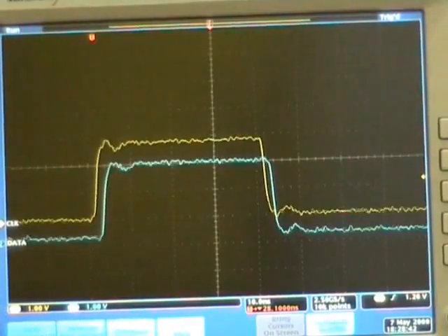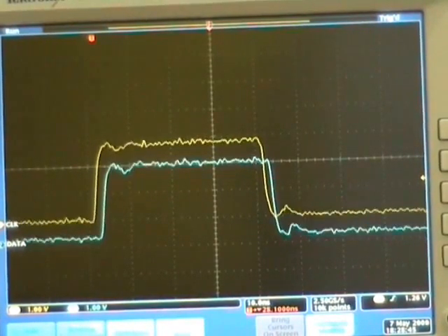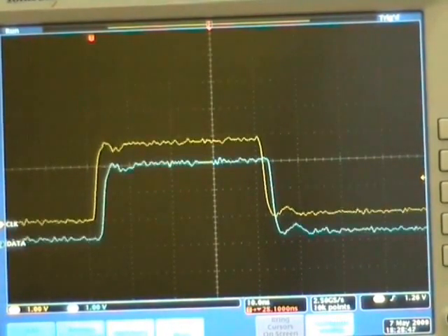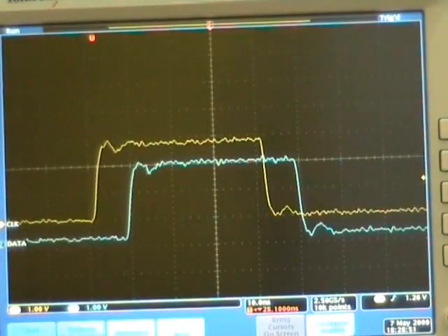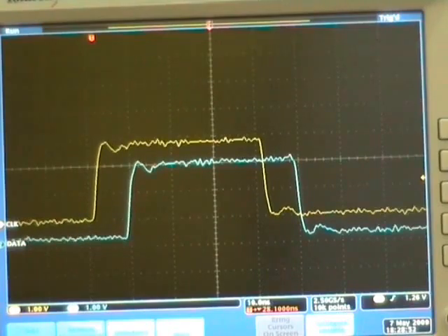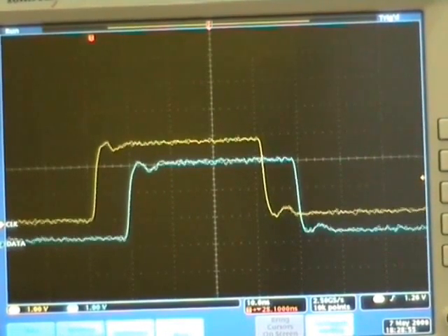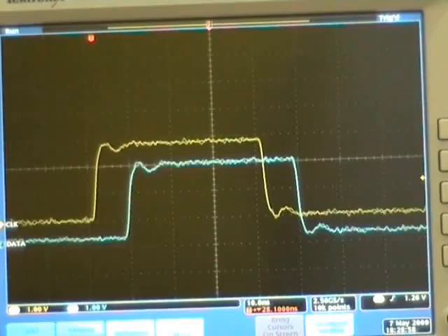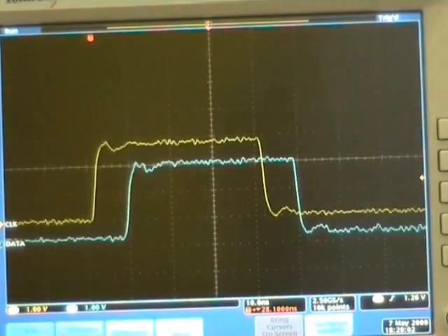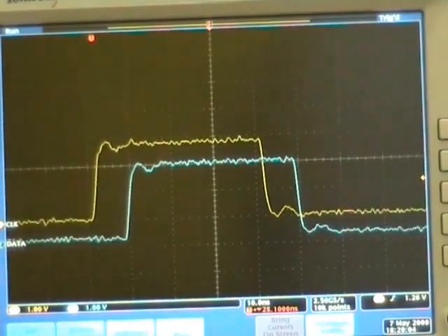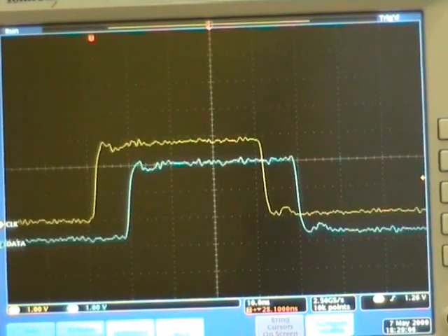Once I program the software, you can see the blue curve moving further to the right. In fact, measurement on the oscilloscope will confirm that the delta time difference between the yellow curve and the blue curve is 8 nanoseconds. This showcases the capability of the I/O module in terms of its flexible edge programming.